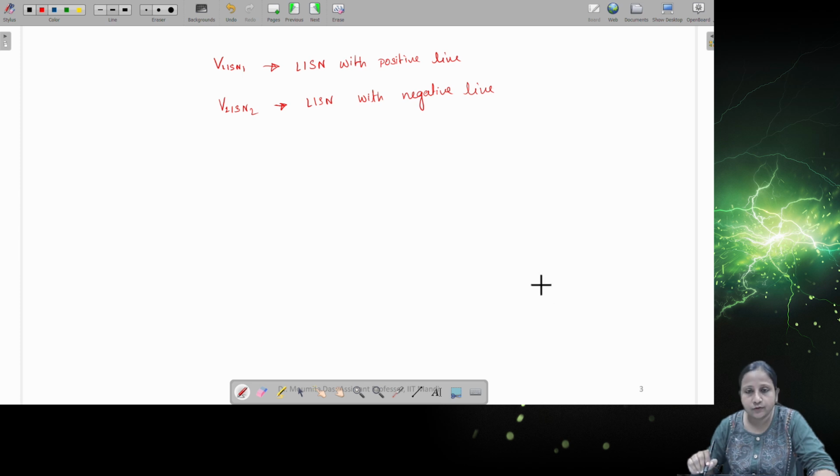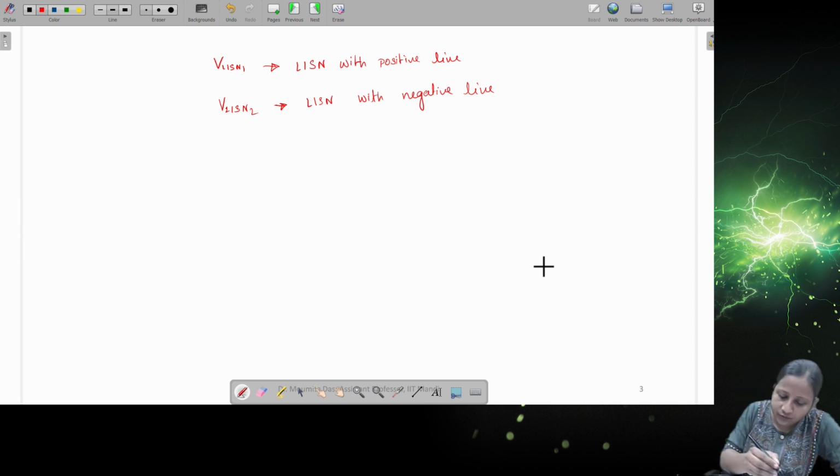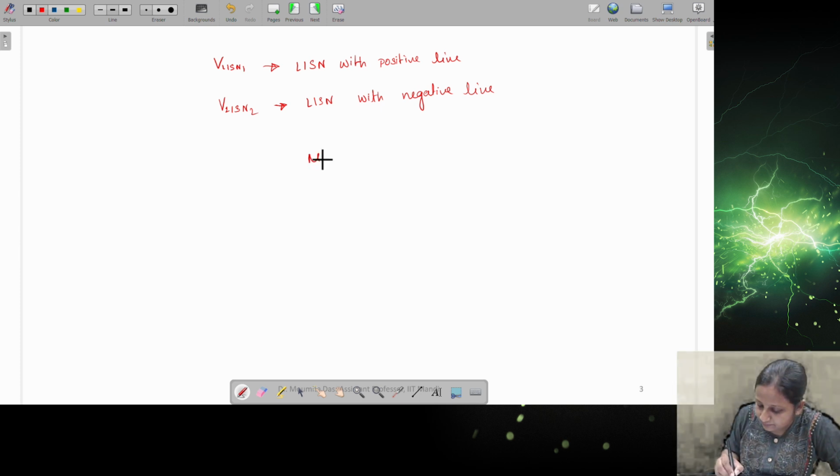So these two pieces of information you can directly get from the converter. You can measure the voltage. You can see the FFT of these noises also, but you will not be able to see the common mode and the differential mode noises. So ideally, the first step of designing a filter is that, if you remember the lecture where I discussed EMI noises, we have to measure.